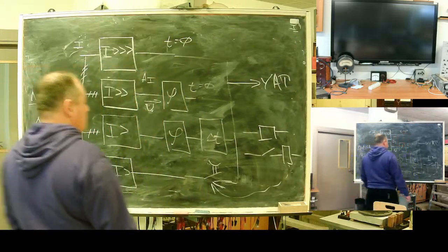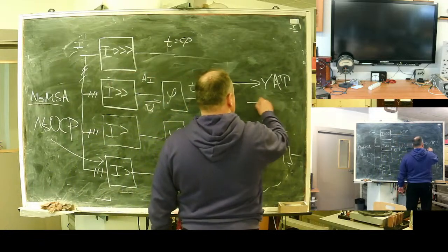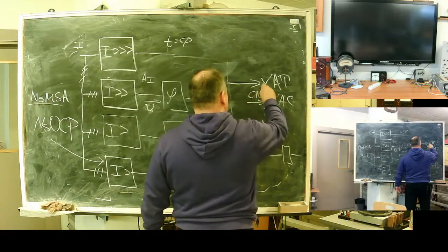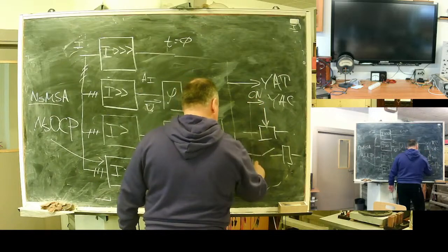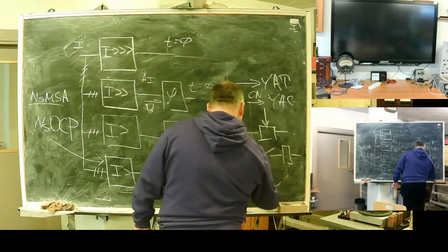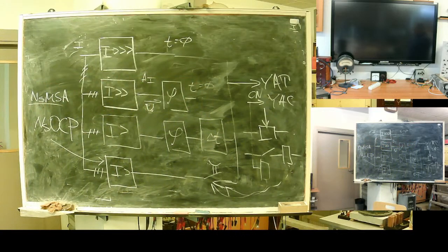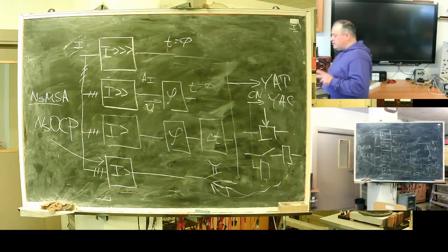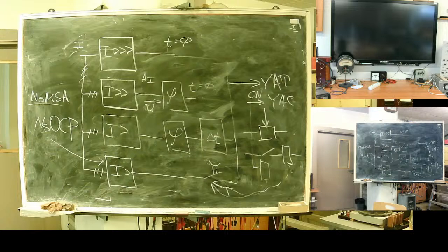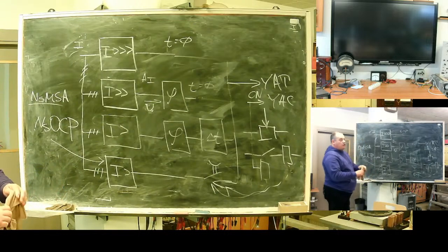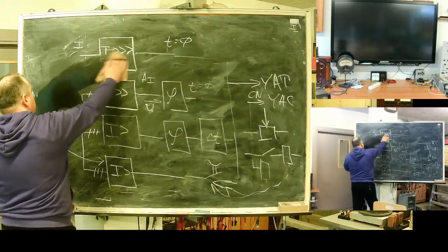Also the command switch on may be used to activate non-selective overcurrent protection. So directed overcurrent protection needs at least speed up or non-selective overcurrent protection for backup because it has a native blind zone for the case of switch on fault. Memory will not help.